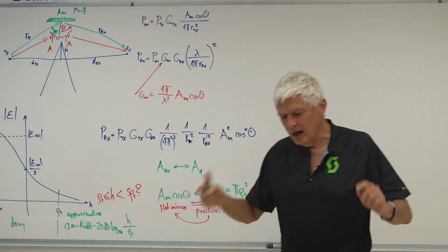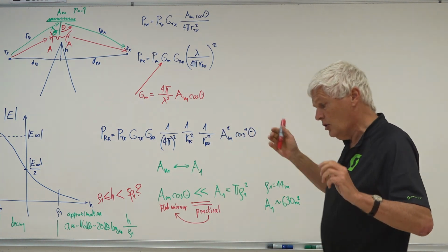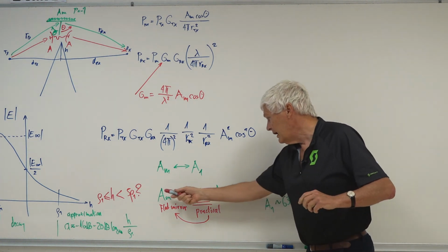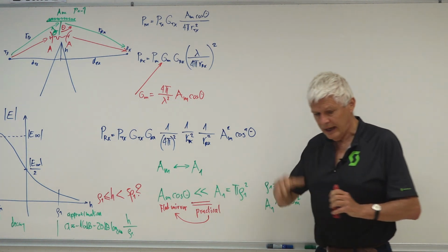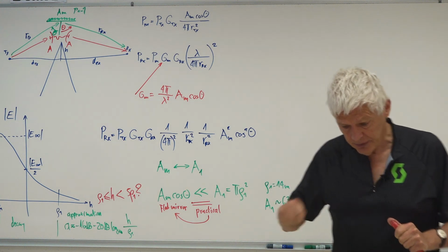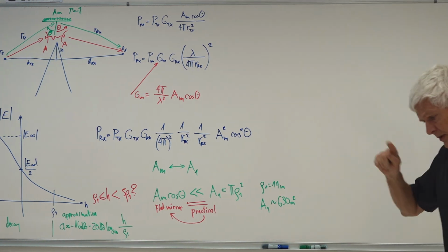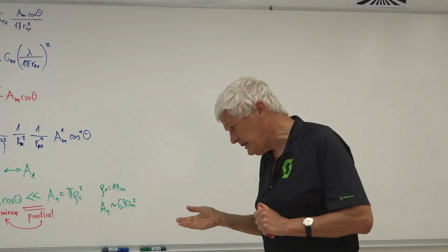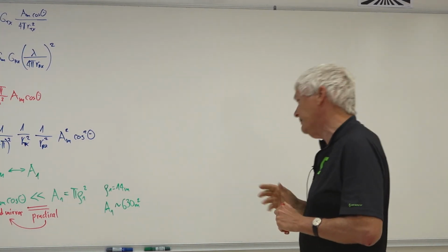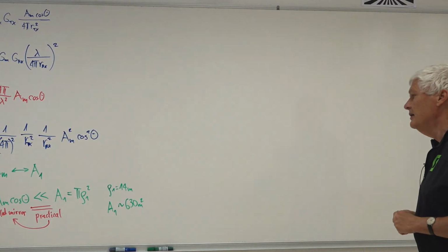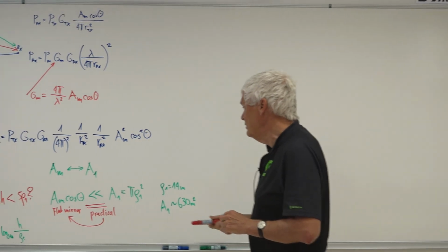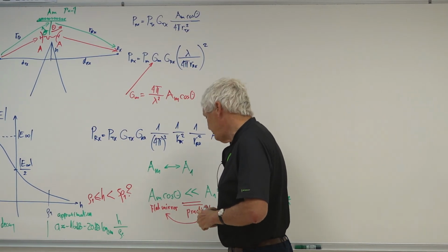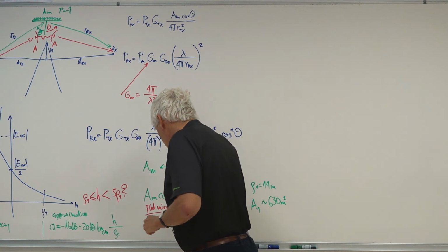We only need a curved mirror when we need to correct the phase. And we need to correct the phase as we raise the area to sizes comparable to the area of the first Fresnel zone. We know that the first Fresnel zone just flips the phase: from the center to the edge of the first Fresnel zone, we have a phase flip of 180 degrees, of pi radians. Because the mirror is much smaller, we need no phase correction here, and a flat mirror is a perfectly good solution.